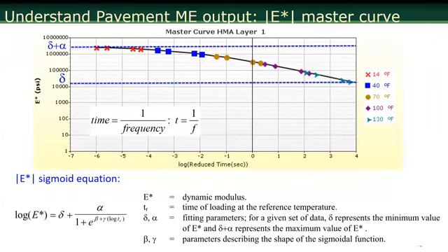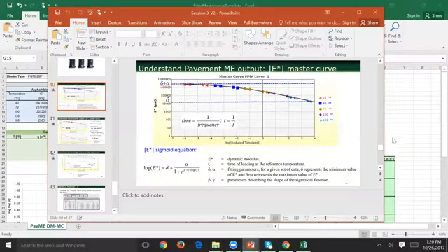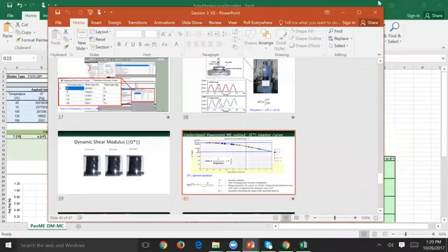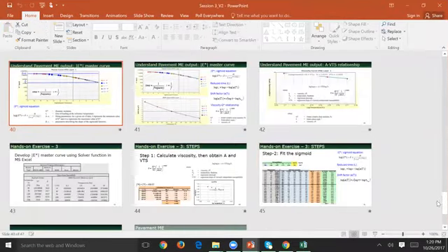If you look at the NCHRP 147 report that I mentioned, and the tornado plot that I mentioned, there is the HMA alpha parameter, very significant, and the HMA delta parameter, very significant. HMA, hot mix asphalt, alpha parameter, and hot mix asphalt, delta parameter. Those are the two things. So in that NCHRP project, let's go to those slides really quickly.